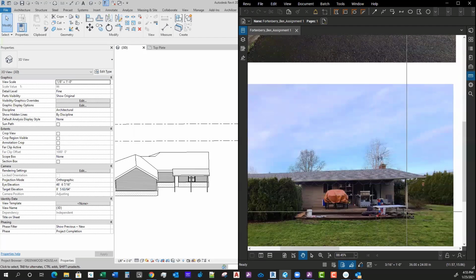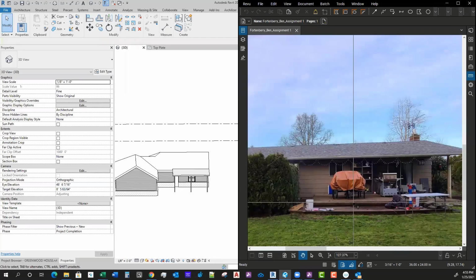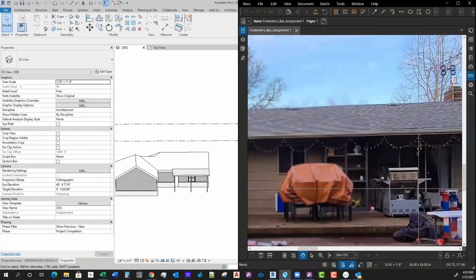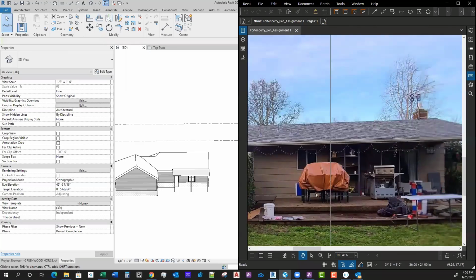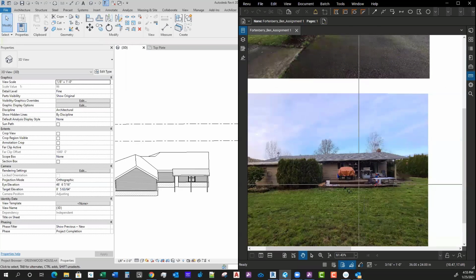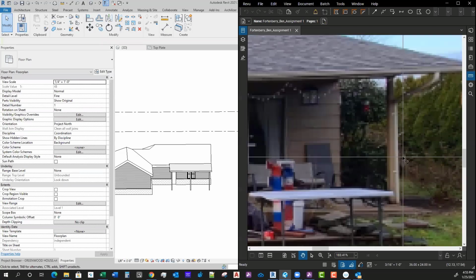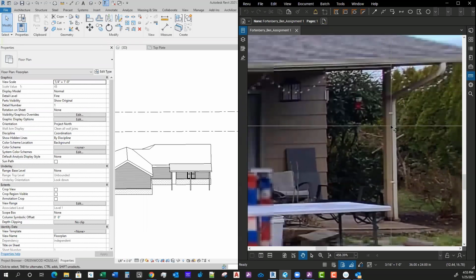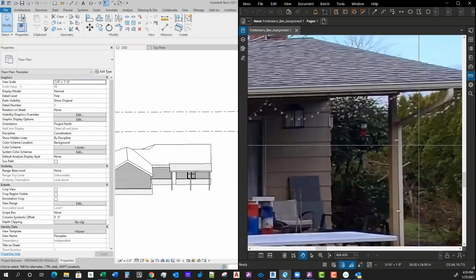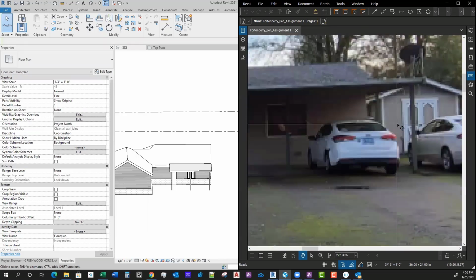And so we can see the back looks like we have the similar condition. And in the back, it looks like, as far as I can tell, they've got some posts out here. Just one post out here, and there's likely one over here behind this outbuilding. And so then we'd need to do the same thing in the back. And that looks bigger than a 4x4 post. Yeah, it looks almost like a 4x8. Yeah, so I'm going to use a bigger post out there.